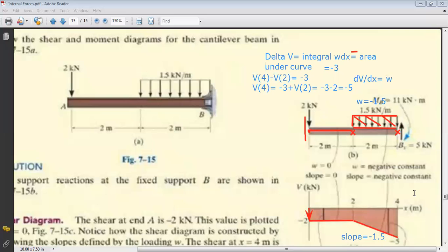I will give you a hint on how you can verify your result. You can verify your result by calculating By. You know why you can do this? Because when your beam finishes, directly after your beam, the shear will be 0, because your beam is in equilibrium. So if you do a cut just after the beam, you don't have anything.